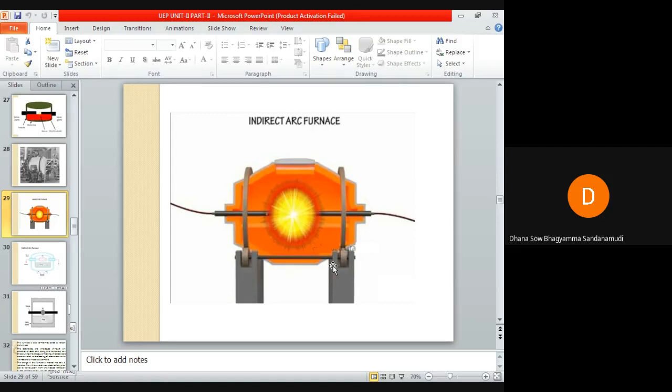The advantages of this arc furnace are that it has a lower overall production cost per ton of molten material, sound casting is possible, thin and intricate, complex designs can be produced, and metal losses due to oxidation and volatilization are quite low. It is also flexible in operation.